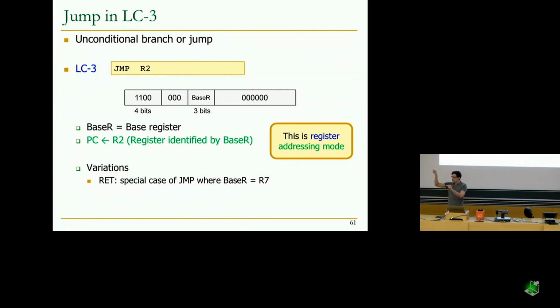So you will jump to another part in memory, you change the value of the program counter, you execute this reduce array or whatever the function or the subroutine is, and when it finishes, it executes this return instruction that brings you back to the place where you called the function. And actually, the place where you called the function is not exactly the jump instruction, but the next instruction. So this R7 is going to store the return address.